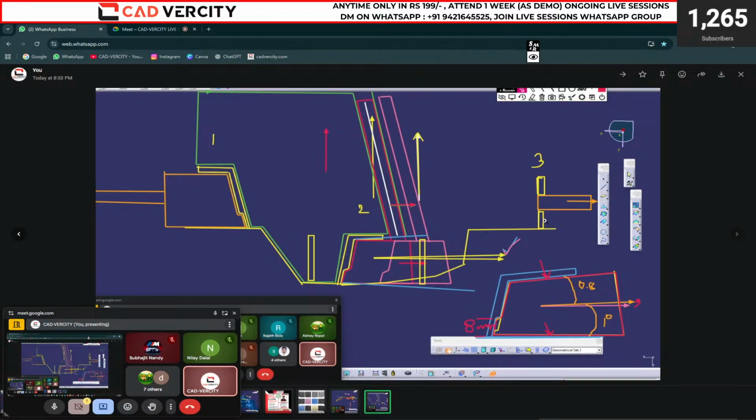Perfect. So most of the time in 3Ds we will have to show slider direction, lifter direction, MTD, parting line. So graining, how to mention graining in 3D? No, we will not consider any graining in 3D. We will only consider the minimum angle required that we received from our supplier or tool expert, like more than 3 degree, more than 7 degree, depending on the grain type.